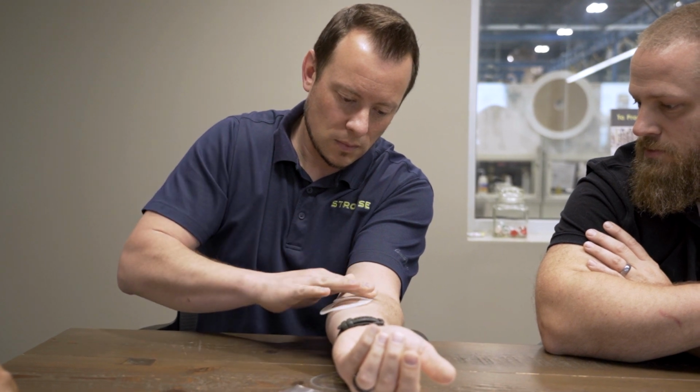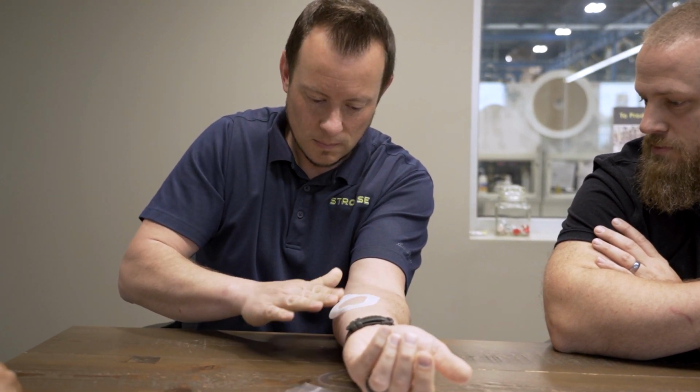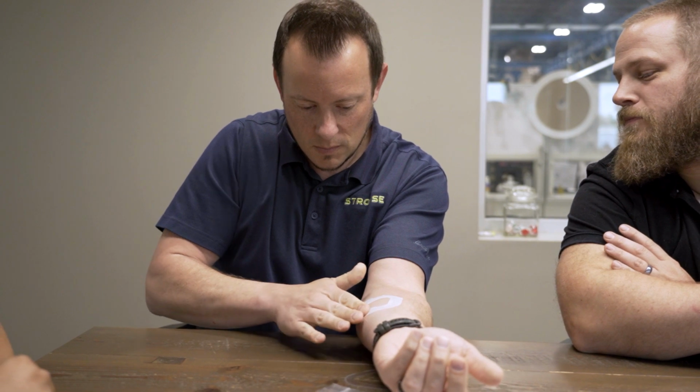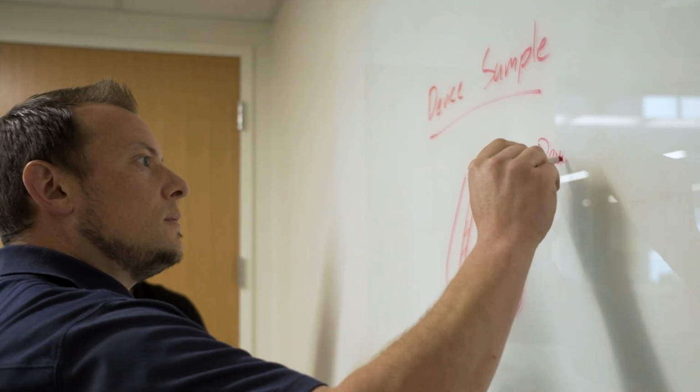We always recommend that you test your product in as close to the same conditions as possible. So temperatures, pressures, forces, the more you can make it like the actual application, the more you can rely on that data. Insufficient testing is another thing that can lead to failures in the field. If you don't proof out the design enough and test enough and build that data set to have a statistical comfort level in the performance of the product, you're opening yourself up to some problems in the future.